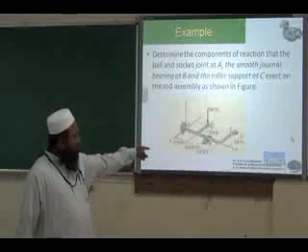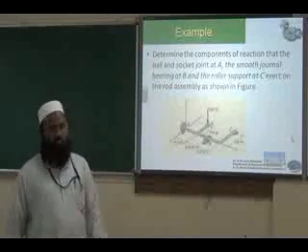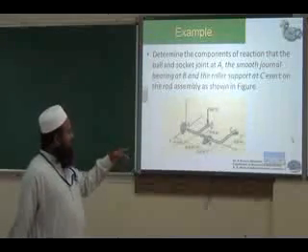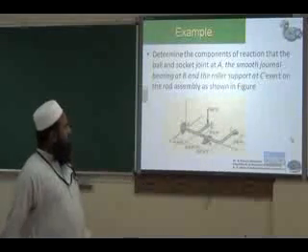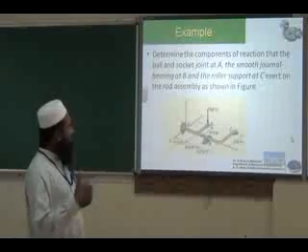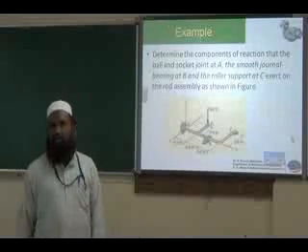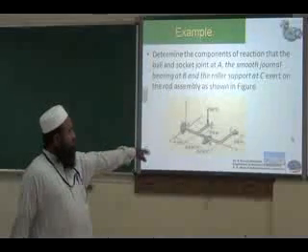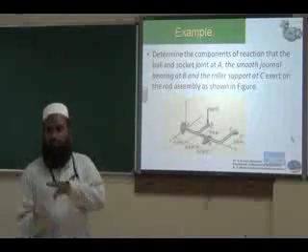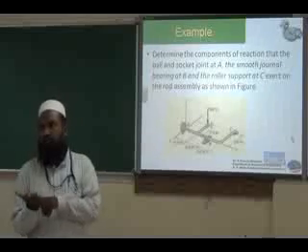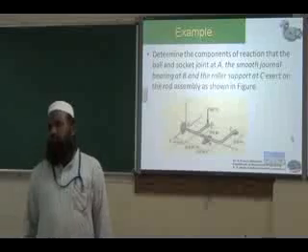And there is a bearing at point B. So bearing allows rotation about Y. But there are only two forces you will have. It can translate in y direction. It cannot translate in x direction. It cannot translate in z direction. So two reactive forces you will have, and at point C only one support. Okay. Only one support is there. It cannot move in the z direction. So only one reactive force.